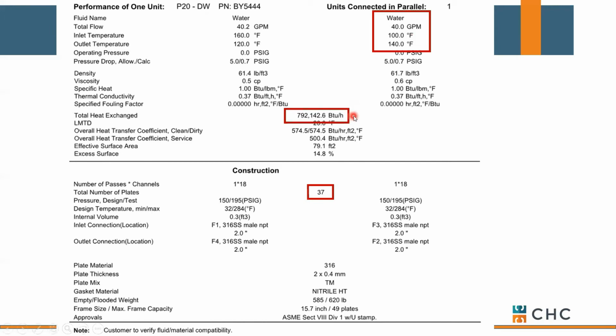What does this mean? It means we're giving people cold showers in the morning, and more than likely we're giving rooms away as part of that. So be careful if you're doing plate and frames for domestic storage tank. Make sure we're sizing it correctly for flow and delta T. That's really important. I stress it because we've seen it happen. Everything becomes a hot priority, and next thing you know, we've got UPS red on a lot of issues.